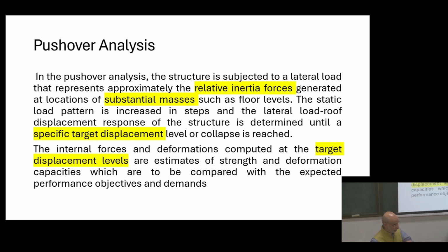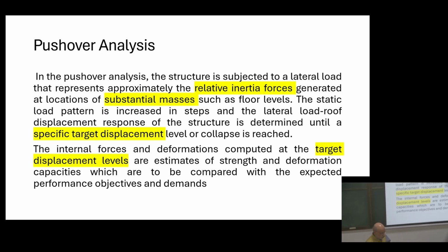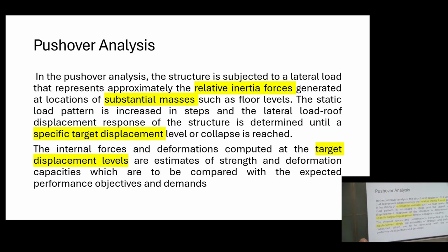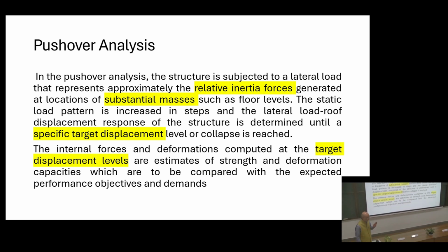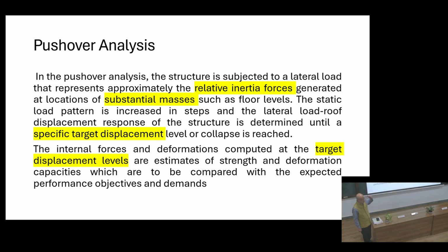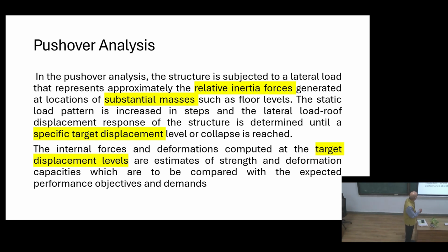Whereas in Cx dot, where x is relative, the C comes into the picture only when the relative deformation comes. Else it will not come. Like in Kx also, the equivalent force, x is a relative deformation. Then K comes into the picture. Else it will not. But inertial force can come. This is absolute. Okay.